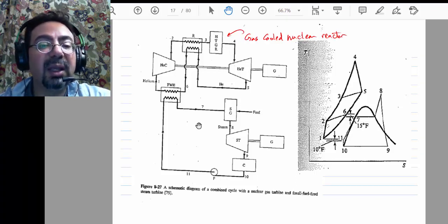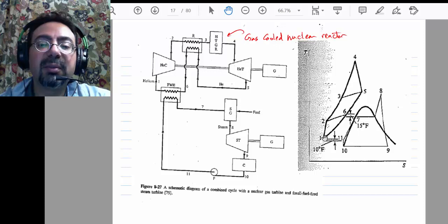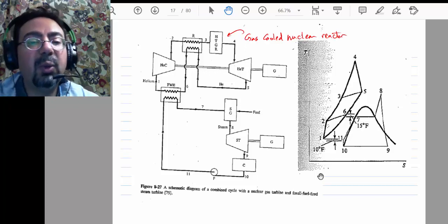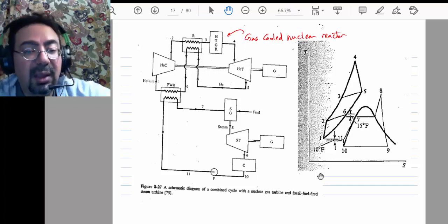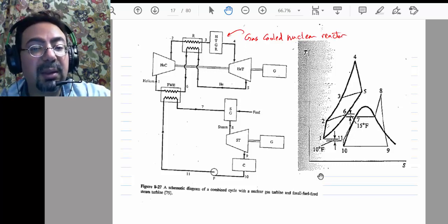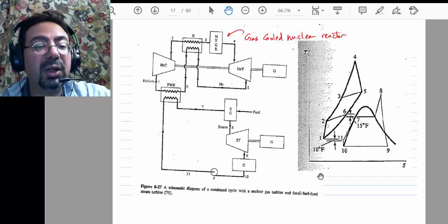So that is a combined cycle steam power plant, and the burner, or the boiler, of the steam power plant is being run by the exhaust of a gas turbine. And so it will look like this. Here is the gas turbine cycle, and here is the steam power plant sitting under it. And that power plant in Owasso will have an efficiency of 60 something percent, compared to 40 something for the Jinx power plant, which is a steam power plant just running on natural gas, not a combined cycle.